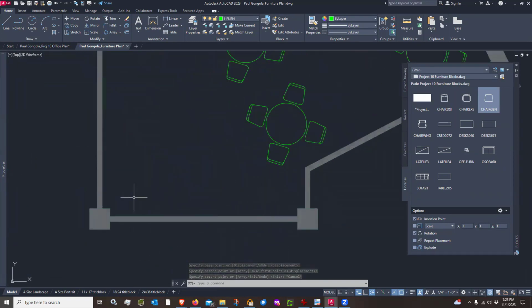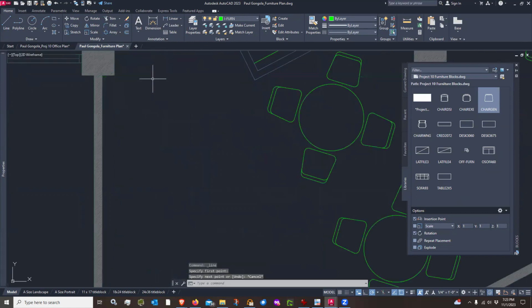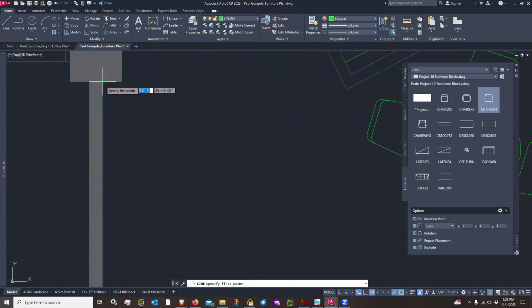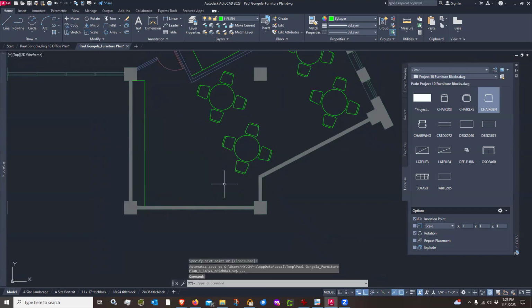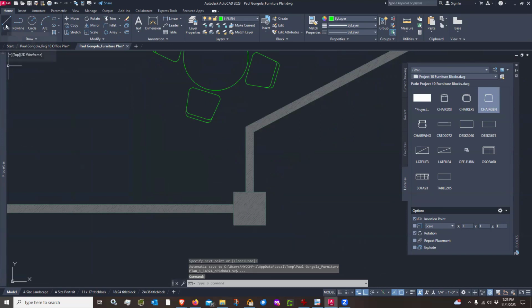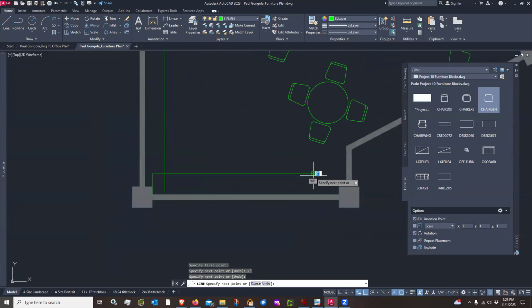I've got some cabinets running along here that are 2 feet. So let me just come straight out 2 feet. Generally speaking, cabinets are 2 feet deep. Not always, but frequently. Put my ortho on. And then 2 feet from along here. I'll start over here, come up 2 feet, and then go, I don't know, to here more or less.